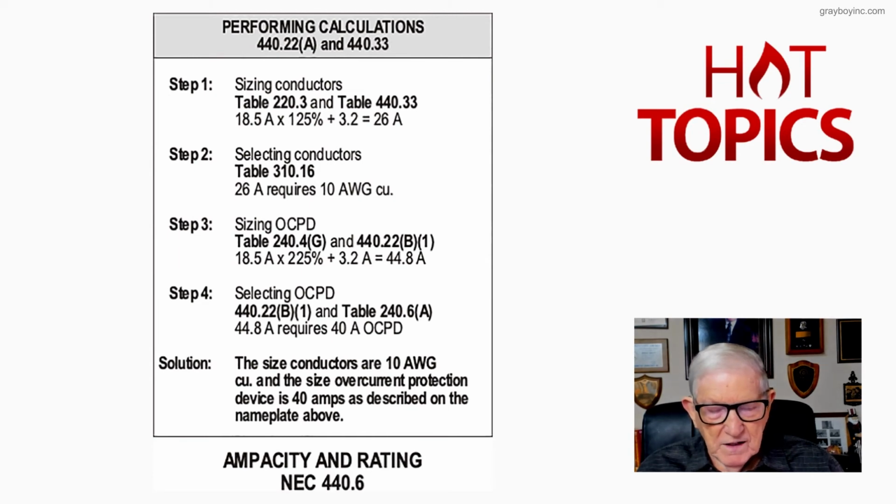And it basically says that we have a compressor or compressors with or without additional motor loads. But we do have a motor load here. We have a condenser motor. So it basically says then that it's item 1, the sum of the rated current or branch circuit selection current, whichever is greater, of all motor compressors or compressor.